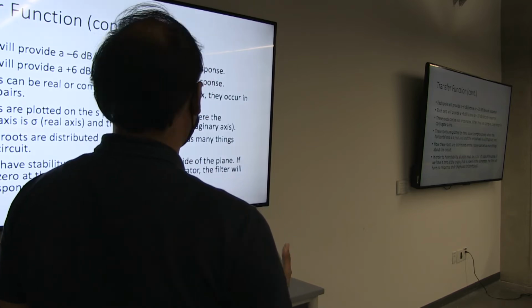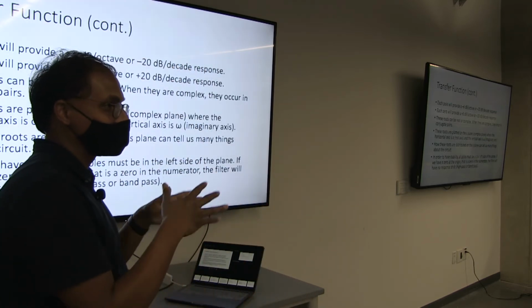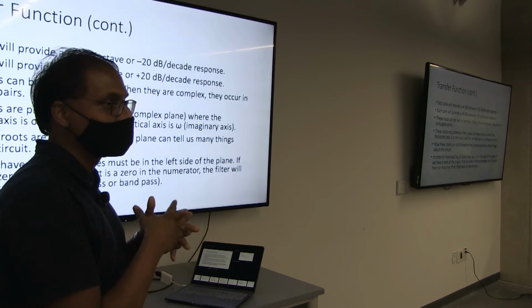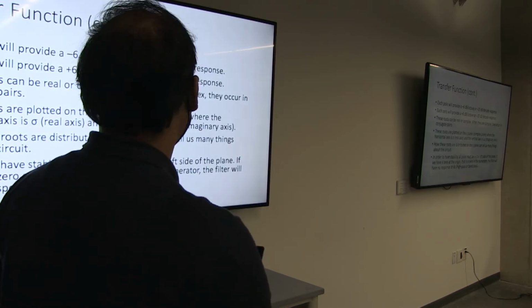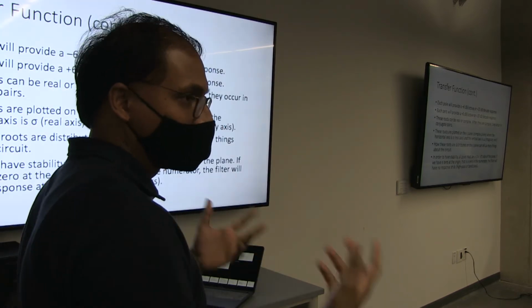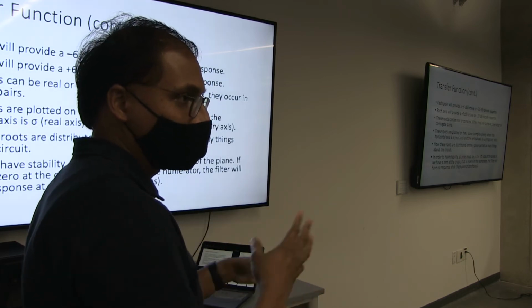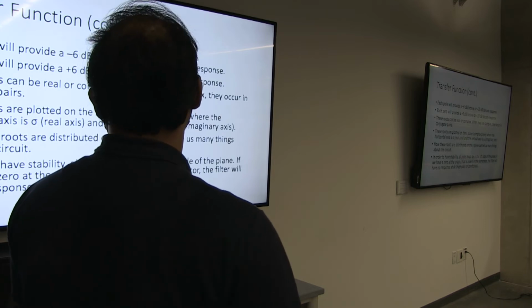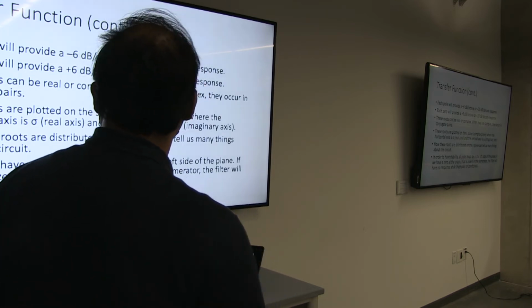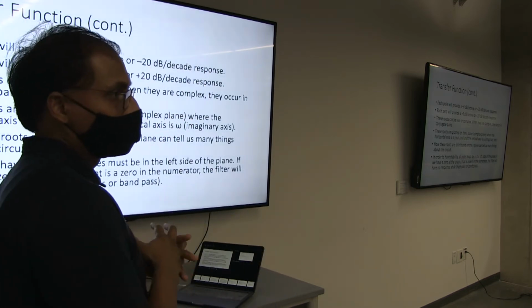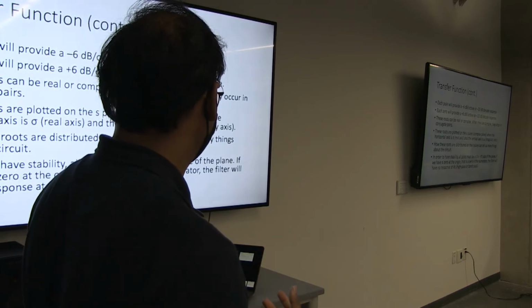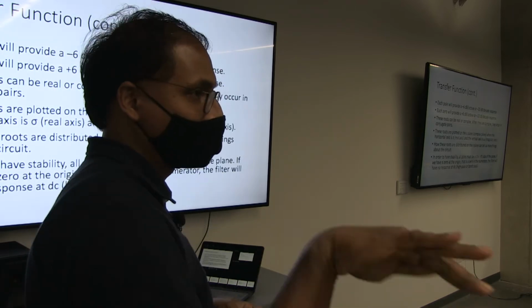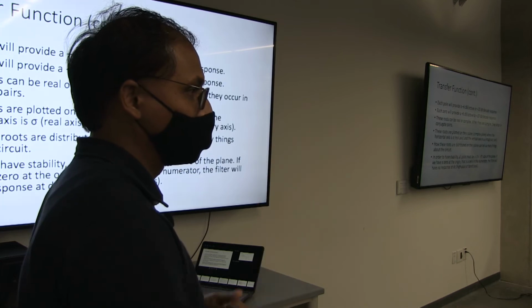So all the roots, again, this is all mapped based on a transfer function in Laplace transform. All the roots can be real or complex. If the roots are complex, they should be conjugate pairs based on the complex algebra rules. And we plot all the poles and zeros on an S-plane with the real axis as x-axis and omega as the imaginary axis.